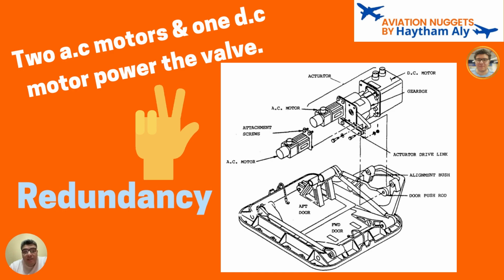This is for redundancy. On most aircraft, two motors will be operated automatically from the cabin pressure controller, and the pilot will not control the opening and closing of the outflow valve. A third motor may be controlled manually from the cabin pressurization panel, just in case the two automatic motors fail.